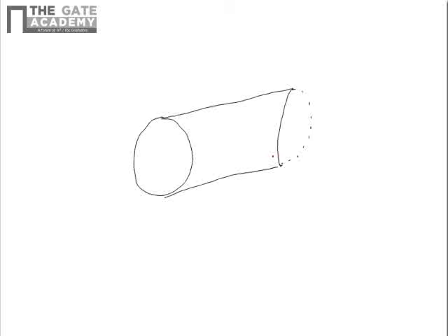As time passes, the performance of a heat exchanger deteriorates as a result of accumulation of deposits on the heat transfer surface area. If we consider the surface, after some time there will be some deposits on the surface. Let us say this is something like this. At both the surfaces, I am only drawing the bottom surface.